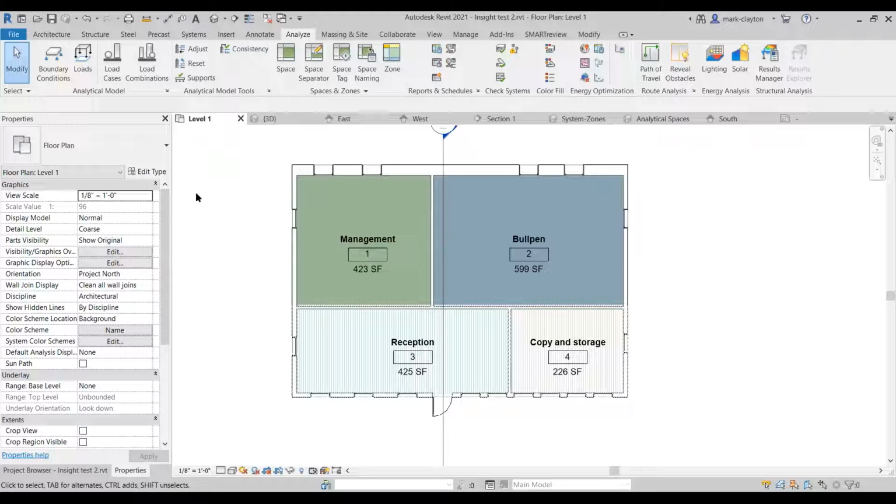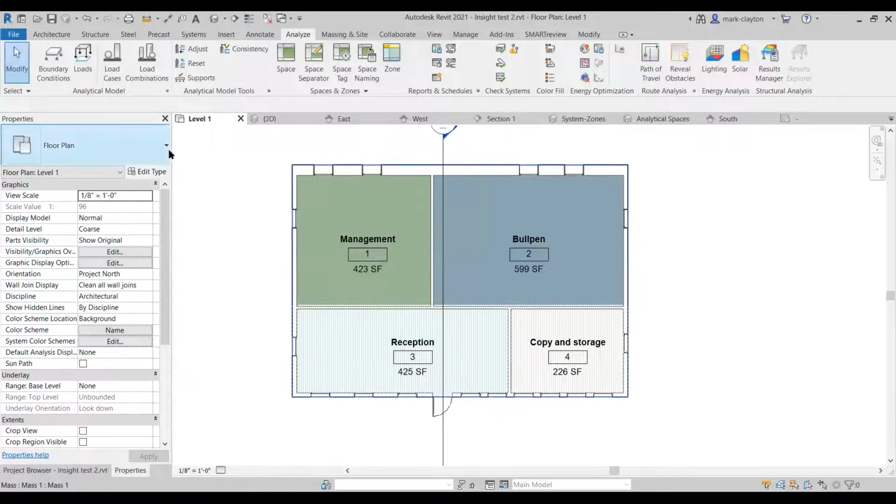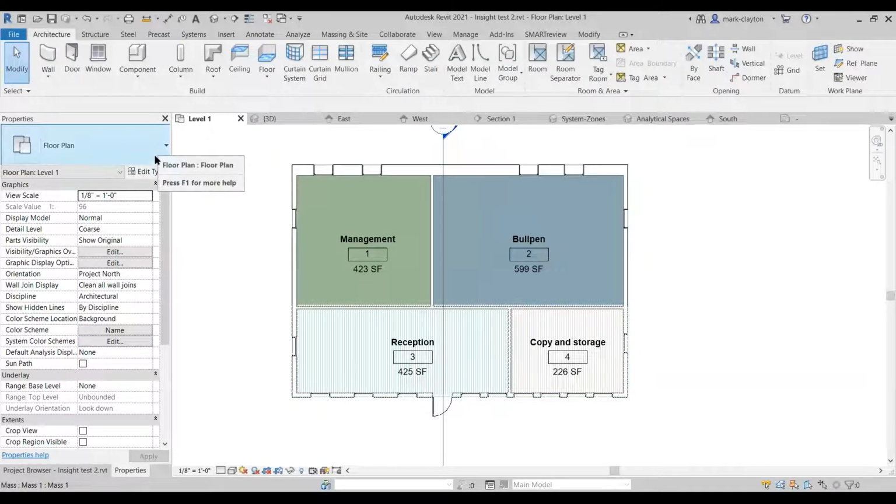Then if you redefine the type, you decide, well, I drew it with red brick, but I don't want it to be red brick. I want it to be brown brick. I just change the type here and all of my drawing changes, right? Now I could go and create another type and select it from the family pull down.